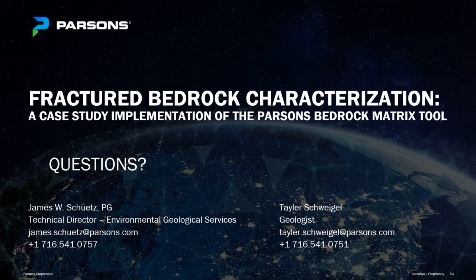Or if you're in a unit that does have a dissolved gypsum seam, you're going to look for that. You're going to try and understand where that is. That might be a marker bed, or any marker bed would be a good example. Okay, we know there's a marker bed within this sandstone. Let's look for that and tie it into our conceptual model so we know where we are in the stratigraphic column relative to the regional geology.